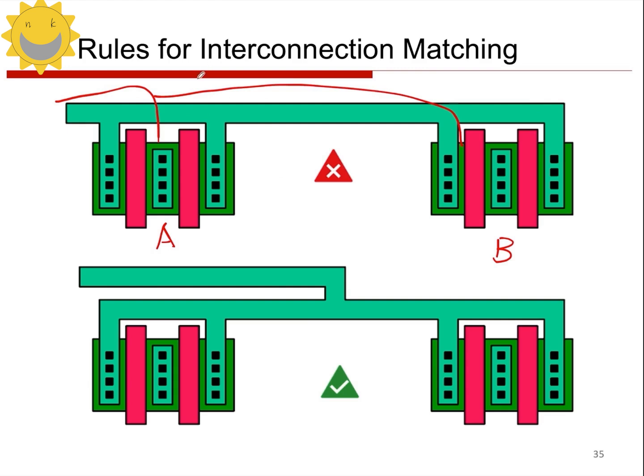Device A's path is short, so its resistance is small. To reach B, it travels a longer distance. Thus, A's resistance R is small, but B's parasitic resistance R is large. If current flows, A's IR drop differs. So, during the journey to B, it has to travel a long distance before reaching B. This way, the integrated resistance R of the connection to A is relatively small, right? But for B, its parasitic resistance R is relatively large. In this case, if a current flows through this line, then it is obvious that A will suffer an IR drop.